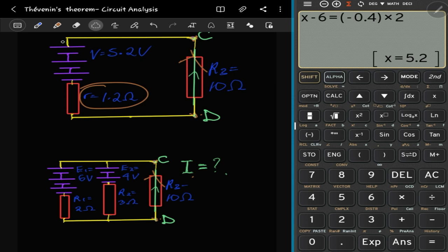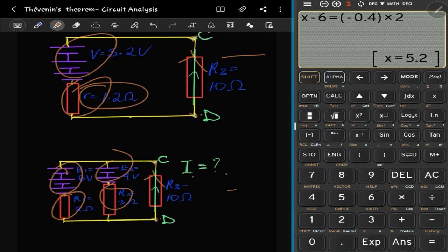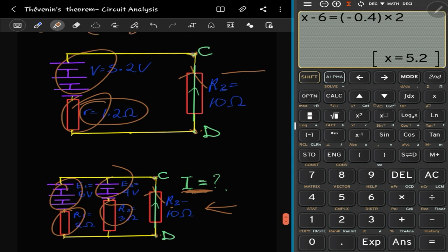That we've simplified all these voltage sources, this and this, into just this, right? And then you simplify this and then this to just this, right? But because we are looking through this terminal as we said, we maintain this R3 here, which is still 10, right? But then what we're seeing, aside from being able to simplify the circuit, is that we are able to find the current passing through this terminal here. So with that we can find it easily now that we have this circuit.